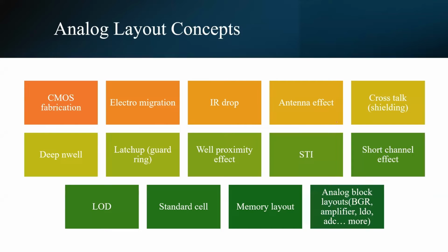Now, while routing is done, we check lots of checks. There is a lot of physics, like electromigration, which is very common and can be found in many circuits. It is itself a big topic, to be covered in the concepts earlier. Then IR drop, which is Ohm's law only. Then the antenna effect, in the part of gate connection.